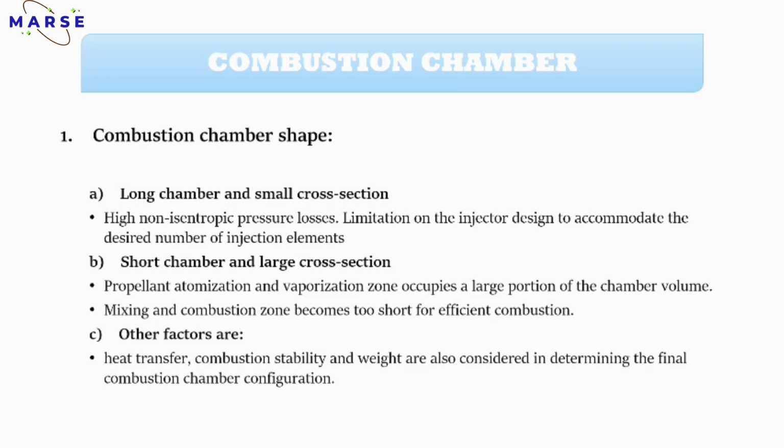The limitations on the injector design to accommodate the desired number of injection elements. Got it? So that's why it will limit the injector design to accommodate the desired number of injection elements. If a small cross section is there, then only small orifices can be used, so the pattern of those orifices will be reduced. So it also affects the combustion process.